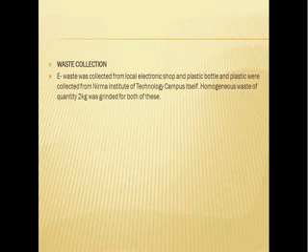So, the waste collection. My study is based on the collection of electronic waste and plastic waste, grinding them into small particles so that they can behave as a fine aggregate in the concrete. For the e-waste, I collected it from a local electronic shop, and the plastic bottles were collected from Nirma University itself. A homogeneous mixture of 2 kgs was prepared by grinding this waste.